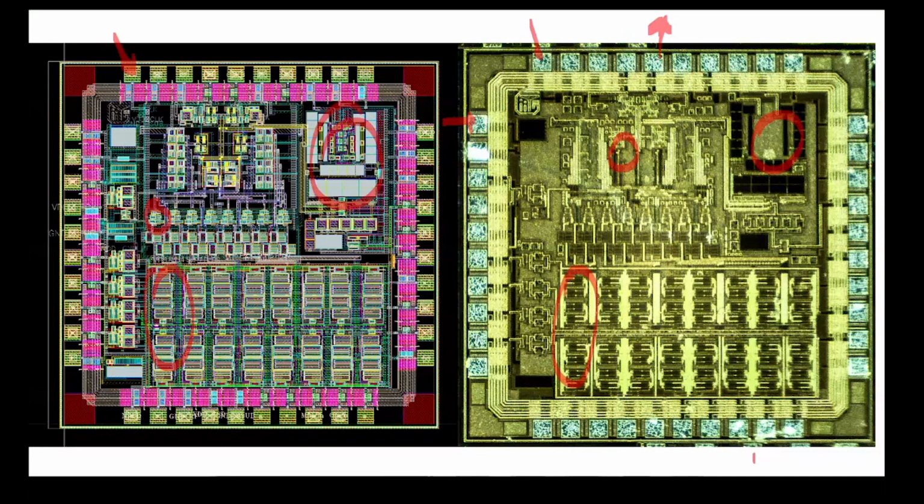So the process is simple. We start with an idea. For an idea, we sit with paper. We read some research papers, or we develop something mathematically if required. Then that idea we simulate. After simulation, if we get a good result, we go for tape out. For tape out, we need a layout. We design the layout, and then we send the layout to foundries.